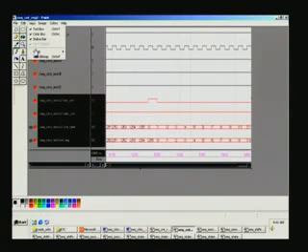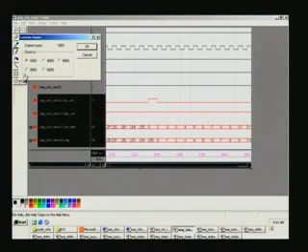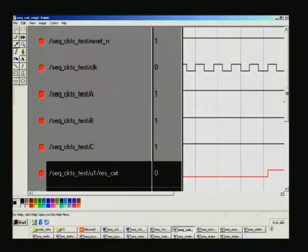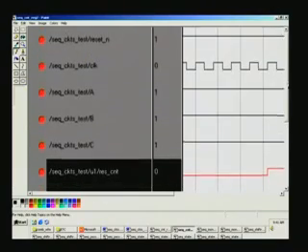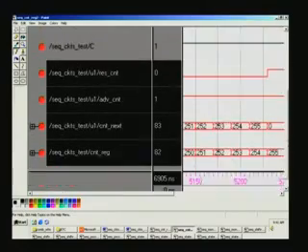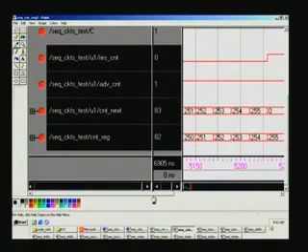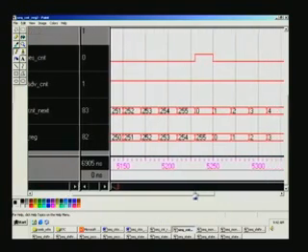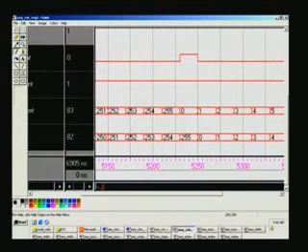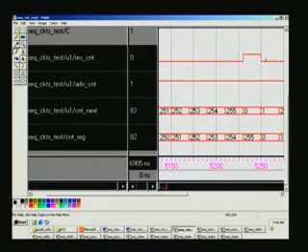Just to zoom here, so you can see this here. The last two are the counters. You can see 250 is the counter edge, and pre-increment is 251, and this happens to be reset count here, and advance count continues to be 1. Therefore, it is counting. Had it gone to 0, it would have reset. So that's how you see that the counter is working.